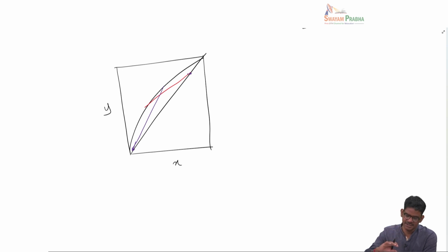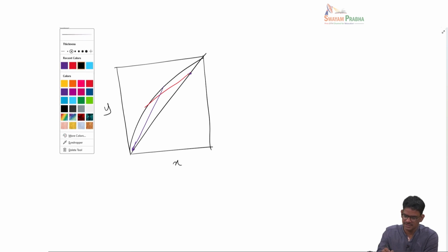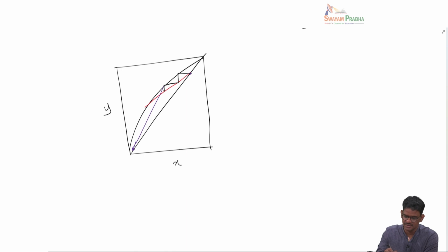So you can see there is an equilibrium line and two operating lines, and we would like to start constructing the staircase diagram like this, and then find the total number of stages. Now I have to make the transition from one operating line to the other at the right point, and that becomes a very critical issue.